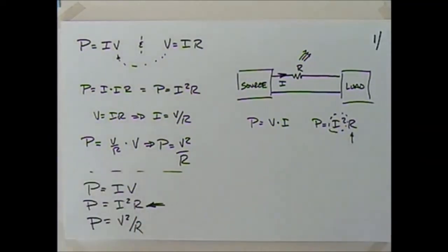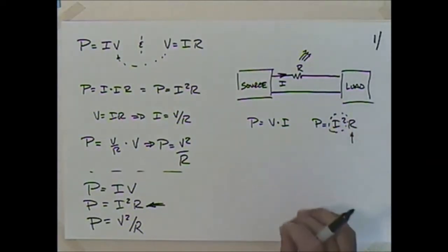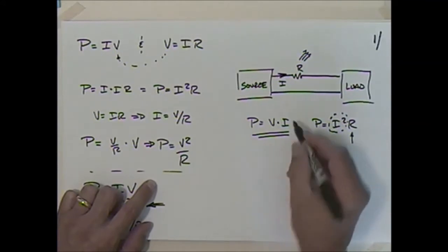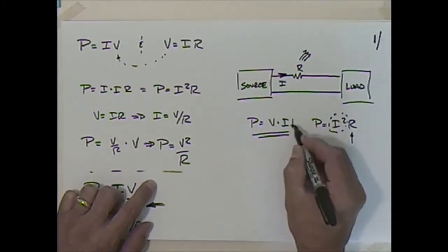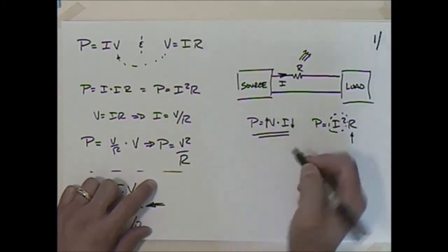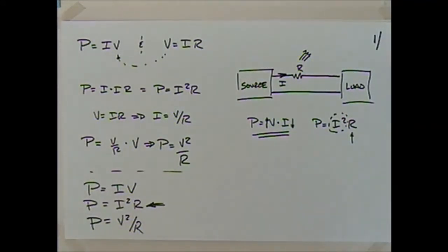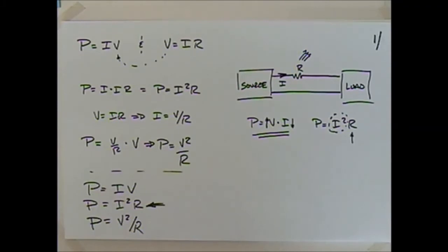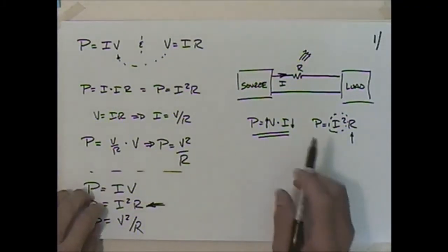Now someone might say, hey, if you're reducing the current, then you're not going to be able to deliver as much power. Well, we can come back to this one, and if I drop the current down, what do I do? I run the voltage up. So that's certainly why you see when we transfer power over long distances, we will be doing it at very high voltages and hopefully lower currents.